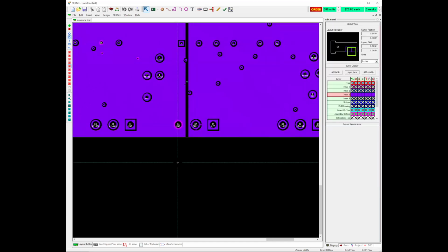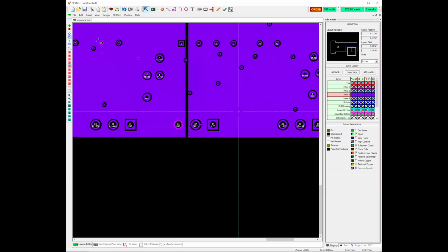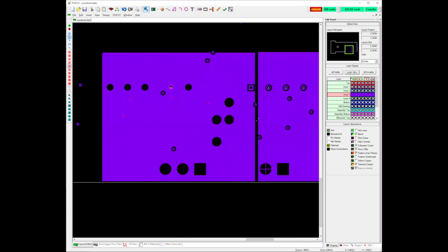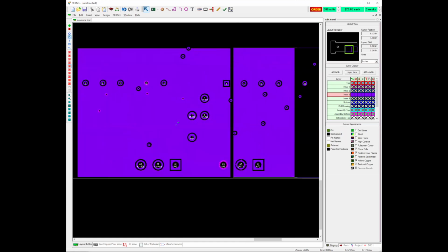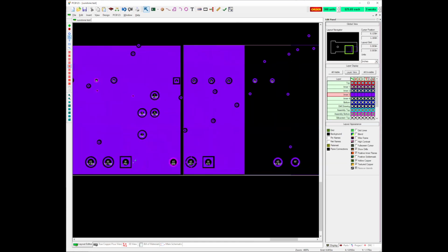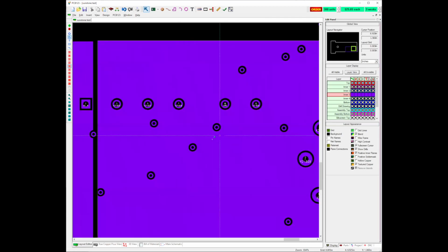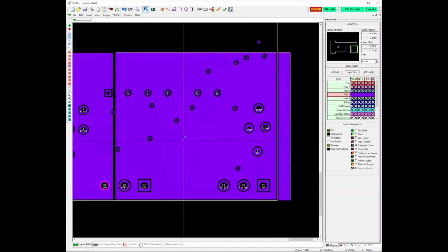Now I've got these two here, 2 planes, GREF1 and ground. And you can see that ground pins are highlighted where they're attached to that plane. They weren't in the negative plane layer that was generated, or with the power layer that was generated. And over here, I've got GREF1 that's connected here. But if there are any ground pins, and there are, they're not connected. So that's the way to let the system protect you rather than attaching something that can tie two different voltages or 2 different grounds or a ground and a power all together